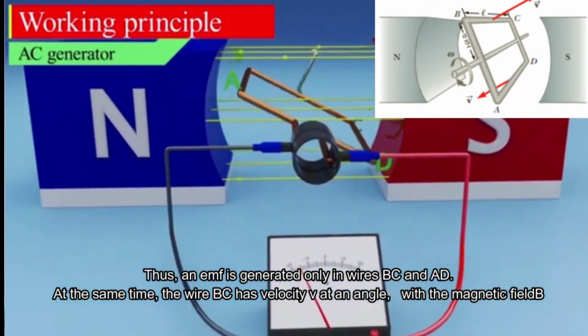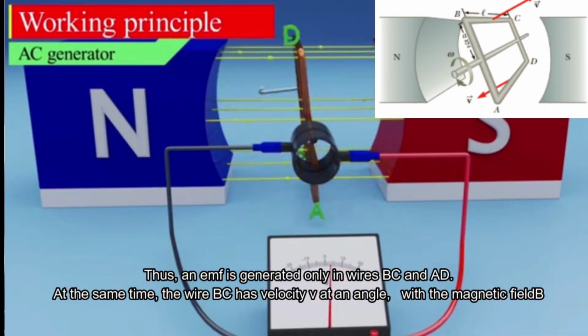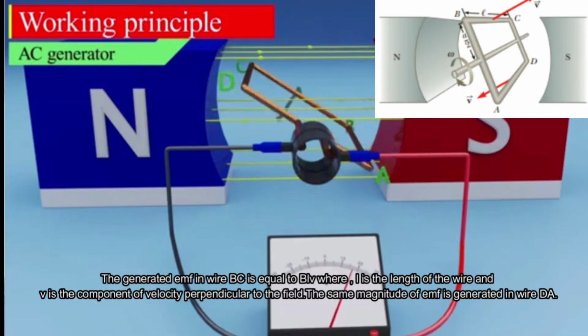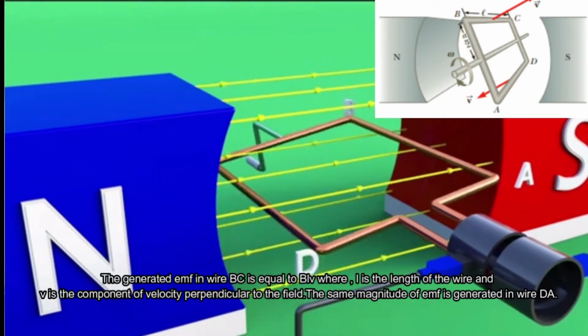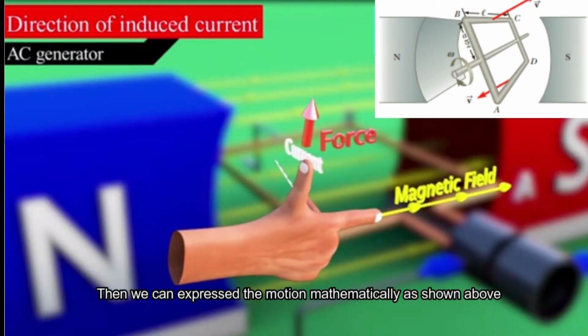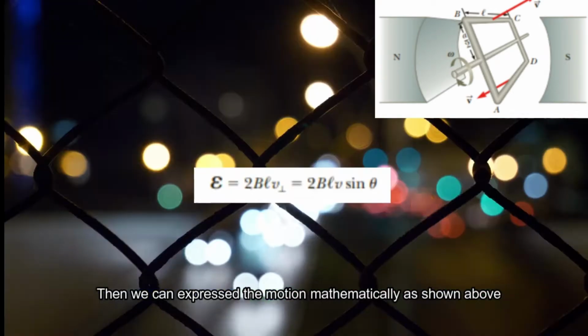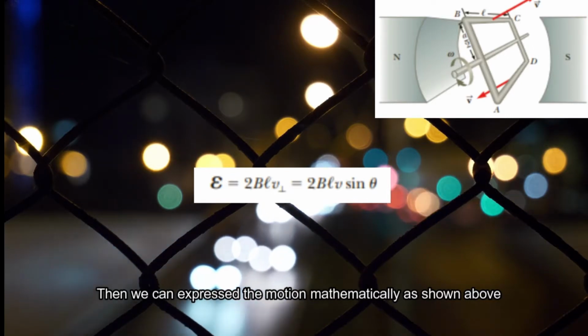At the same time, the wire BC has velocity v at angle theta to the magnetic field B. The generated EMF is equal to BLv, where B is the magnetic field, L is the length of the wire, and v is the velocity component perpendicular to the wire. The same magnitude of EMF is generated in the wire DA. Then, we can express the motion mathematically as epsilon equal to 2BLv equal to 2BLv sin theta.